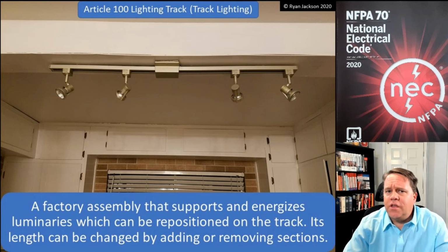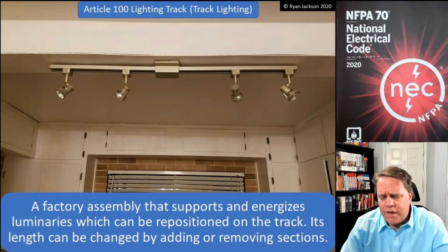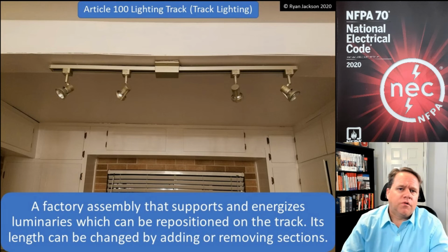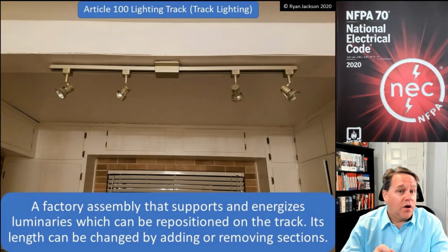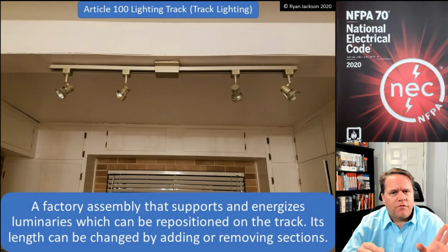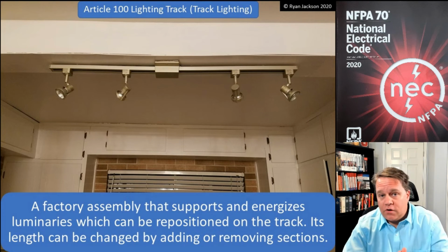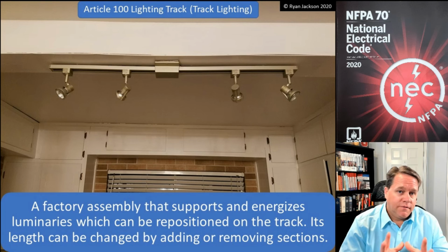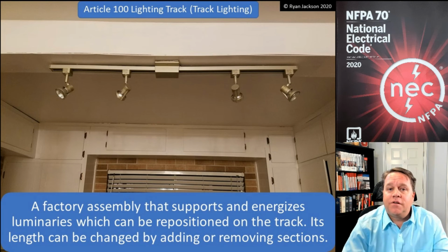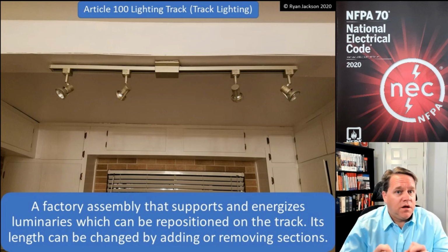A couple of interesting things about lighting track as it relates to the code. I'm going off the top of my head here, but I think it's 220.43, talks about feeder and service calculations for lighting track, and it says for every 2 feet or fraction thereof, you have to include 150 volt-amps to your load calculation. It's imperative to understand that that is only for the feeder and service calculations. It does not limit the length of lighting track on any given circuit.